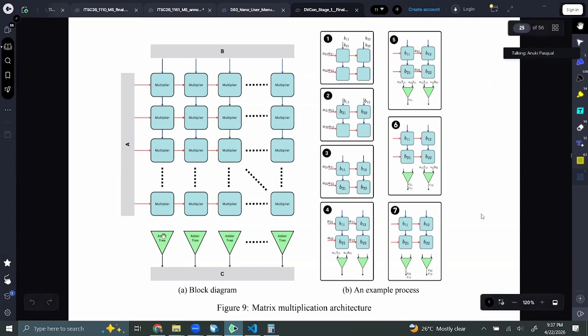The adding part is done by this adder tree. There are multiple adder trees. The output will be one row of the first matrix and one column of the second matrix, added, and then at each cycle you give a new row and a new column of the two matrices. It's a bit complicated, but search for systolic arrays. It's a very common thing used for hardware acceleration, and there should be a lot of resources explaining that.